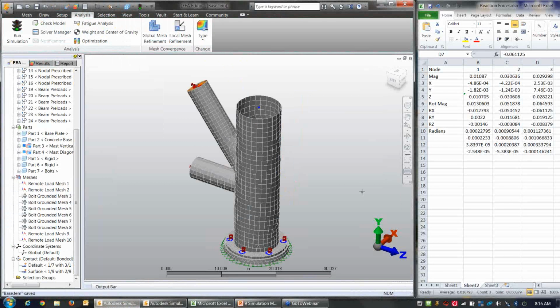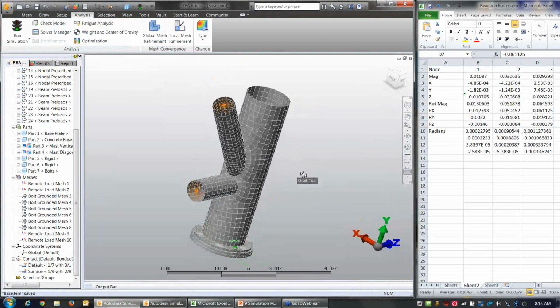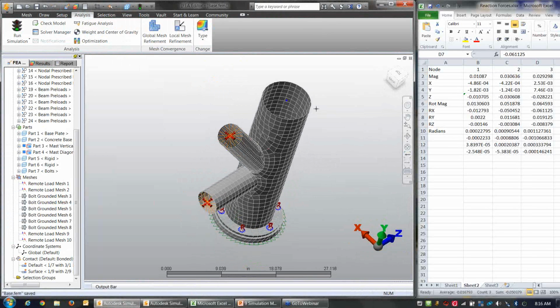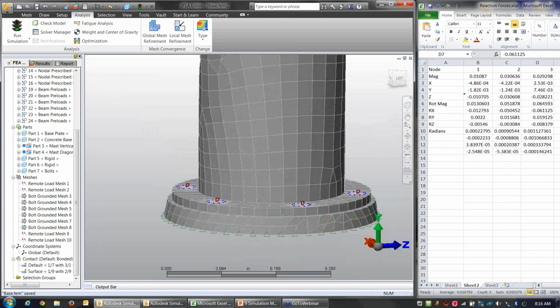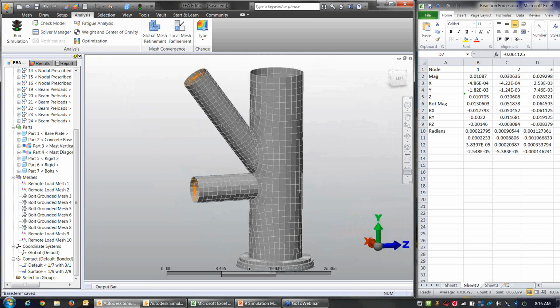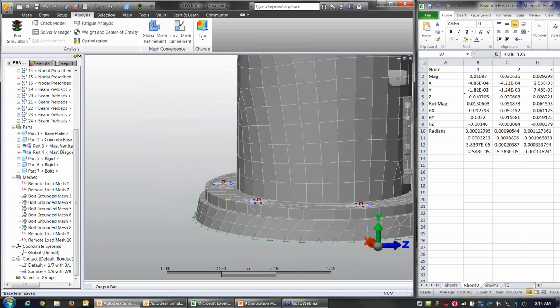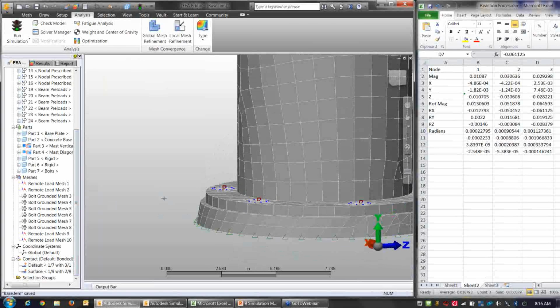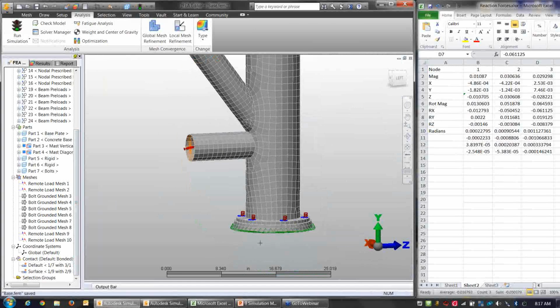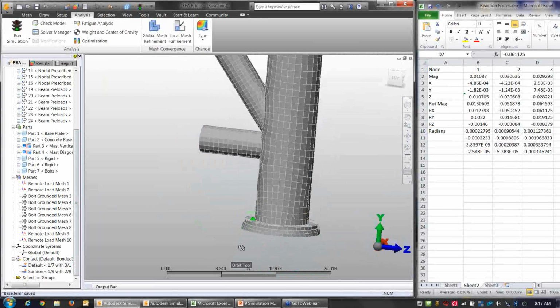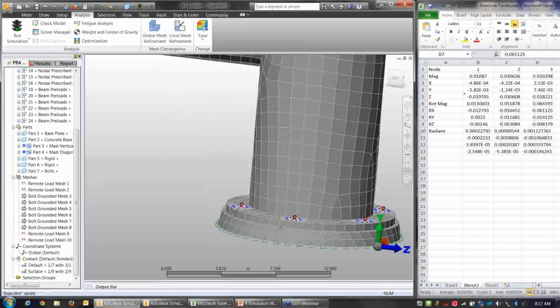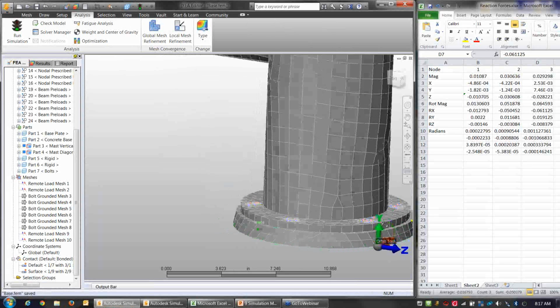Now we go on. So here is our submodel. We're looking at a 3D representation, or 3D elements. Well, sorry, that's incorrect. Beam elements are 3D. We've got shell elements or plate elements, more specifically to model the beams themselves. And I've got a solid plate here to represent our mounting plate. And this bottom part is a base plate. That's our concrete fixture that we're mounting to. We're not interested in the stress in it. We just want to use that for the surface-to-surface contact that the mounting plate or the base plate here will experience when mounted to that concrete pillar.